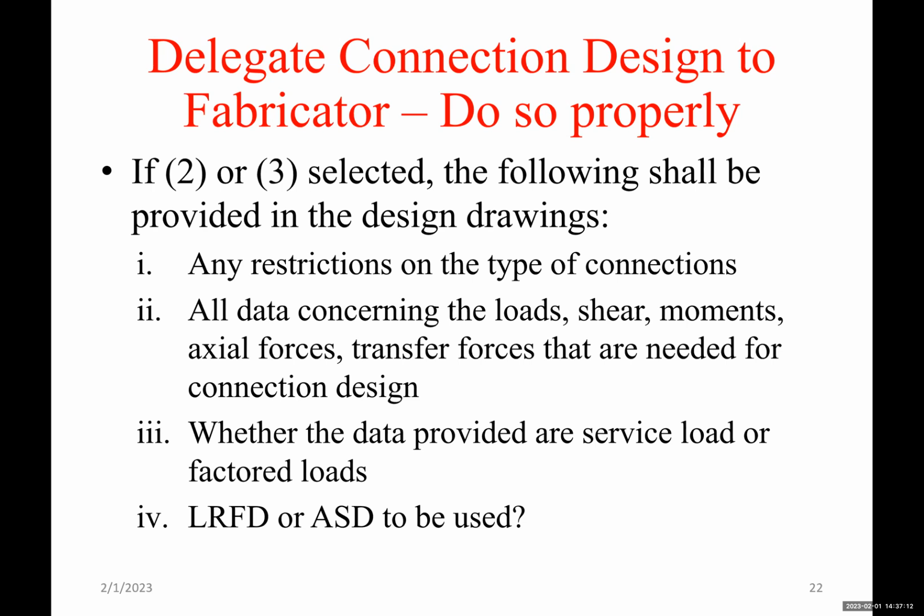Indicate that, not because you don't like this type of connection, or you prefer this over that, or that's what's typically used in practice over that. So maybe this fabricator prefers something else. Provide all data concerning the loads, shear, moments, axial forces, and transfer forces that are needed for the connection design. All the data that are needed for connection design, have it there.